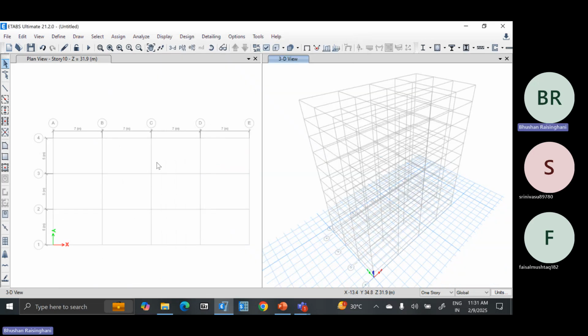First we'll model everything, and then you can also rotate. But once you rotate the grid, that does not mean the element is also rotated. So you have to be very sure when you are modeling: if you want a rotated arrangement, you rotate the grid and also the element while modeling from the initial level itself, not later on. First, I will save the model.